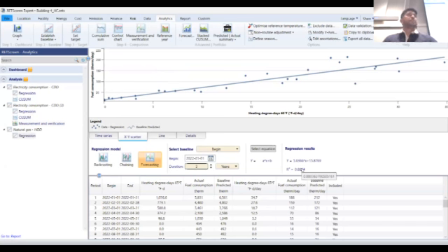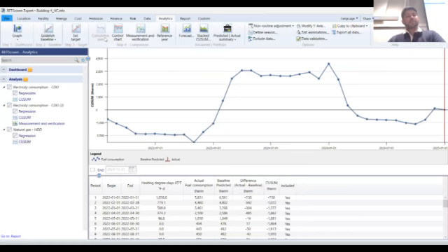What I'm essentially doing is creating a baseline. Click on cumulative sum to see when the energy starts going down. So this is 22. It increases in 23. There's no energy saved. There's a little bit of drop here in 23, but the biggest drop comes after December 2023. That means something happened by the end of this year which has reduced my natural gas.